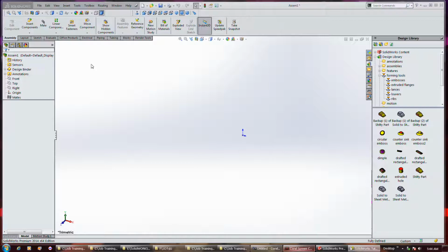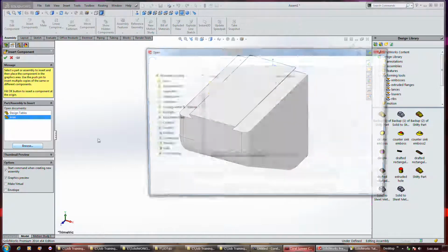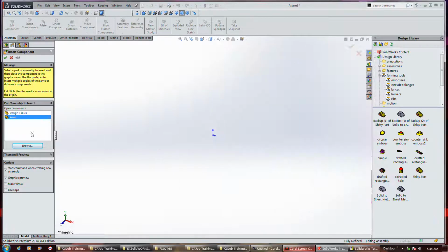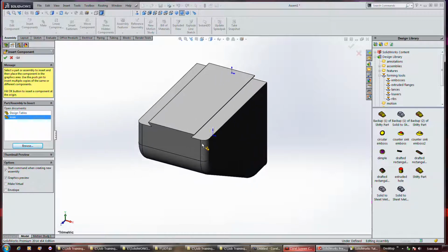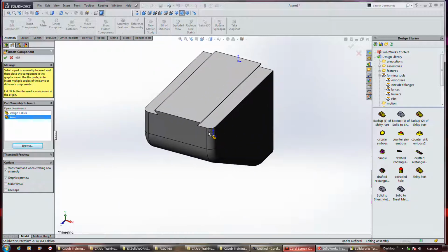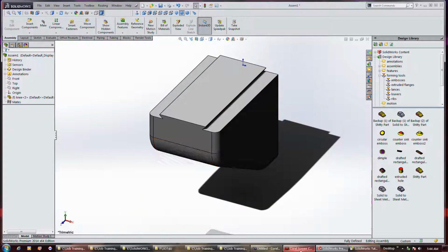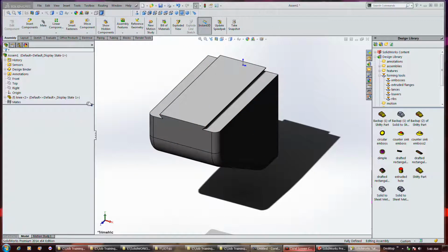But let's go about that again, just to make sure. Okay. See, so that snaps to it when you choose it, even though it's not by default on the origin, it does snap to it just like that. Now the F means fixed. You see that little F in parentheses, that means fixed. And if you expand this, the 1 means this is the first instance of the part.